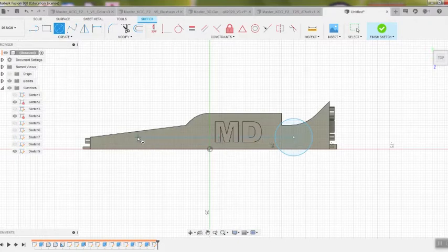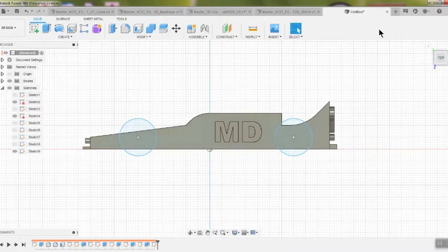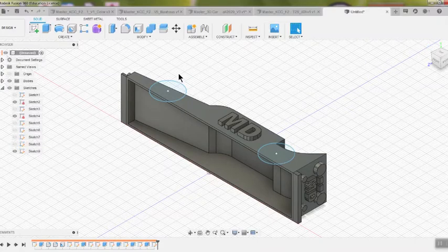Notice we have the dotted line. And let's left click and release. And let's snap this also to 15.620. Left click and release. And there we got 2 wheels. And let's finish that sketch by left click and releasing. And let's go back to the home button, left click release. And now we want to extrude the wheels, right?